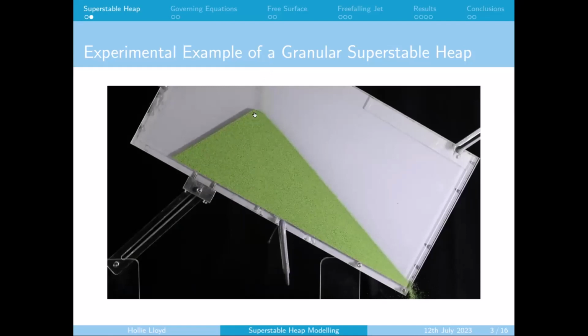So material will just flow in the domain, down the free surface and exit the domain, and the pile will remain unchanged. But this pile still can't drain so long as this free surface flow is there trapping it in, because all of the material flowing out is the material that's flowing in. But you can see that once the inlet is cut off, then this pile is free to drain. It wants to, because this angle is steeper than the initial 22 degrees that it wants to remain static at.